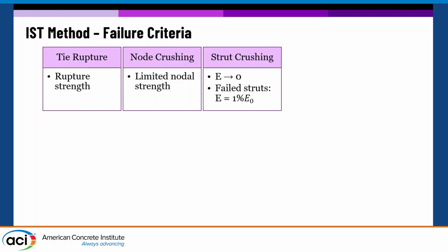So you just want to predict lower strengths than in the test. Lower strengths, proper failure mode, and consistent with logic. Like more stirrups will give you slightly more strength. Even if not much, there should be more. But all these strengths depend on the softening factors. So if your softening factors are not logical with, let's say, the spacing of stirrups, then you will suddenly have completely different results from modeling.